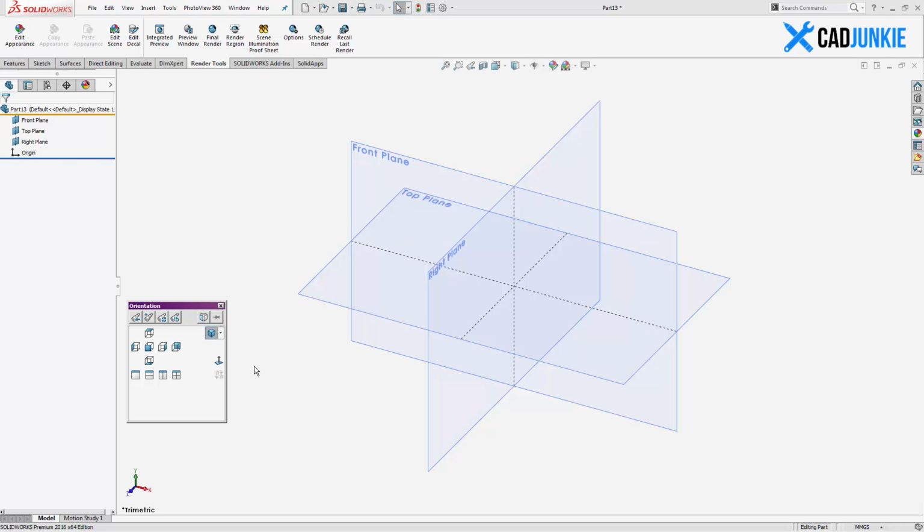Just be warned that you can change the views so that you are ostensibly working Z up in SolidWorks, but that change is not anything like pervasive within the application. So that, for example, your canonical sketch orientation will be sideways. Whenever you create a sketch, the horizontal constraints will be vertical and vice versa, which is very confusing. Also, whenever you look normal to a sketch plane, your whole car is going to turn sideways. It's just weird. So I don't recommend doing that.